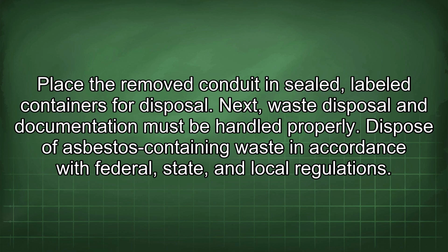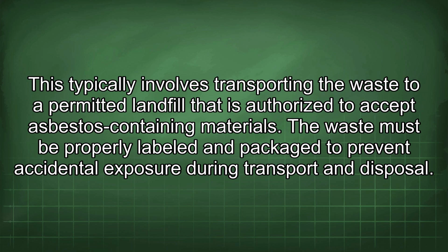Next, waste disposal and documentation must be handled properly. Dispose of asbestos-containing waste in accordance with federal, state, and local regulations. This typically involves transporting the waste to a permitted landfill that is authorized to accept asbestos-containing materials. The waste must be properly labeled and packaged to prevent accidental exposure during transport and disposal.